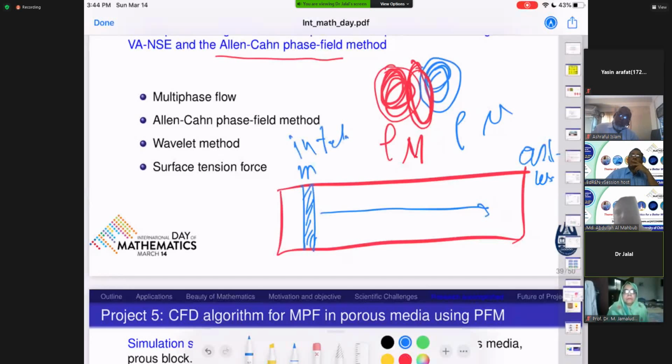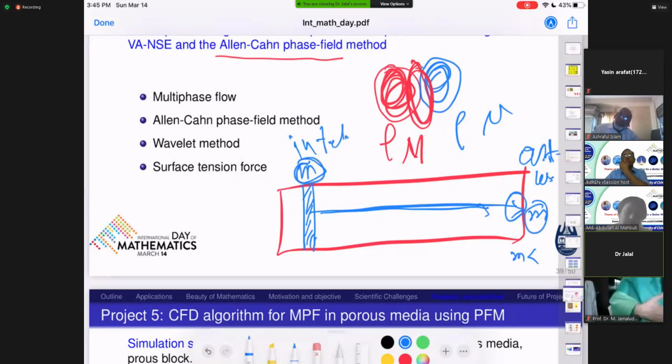When the flow or fluid comes here at the end of the output side, so I have a mass m here. Now I have to check, do I have a mass m here or is it less than m? So if this m and this m are the same, I can say that mass is conserved. So my technique and my simulation are very much correct. Okay. So that's why we consider the mass conservation analysis here.